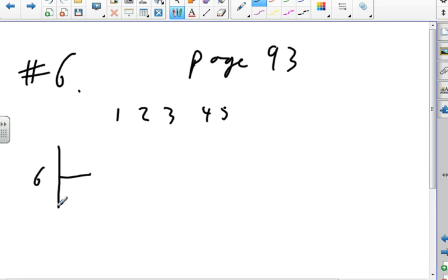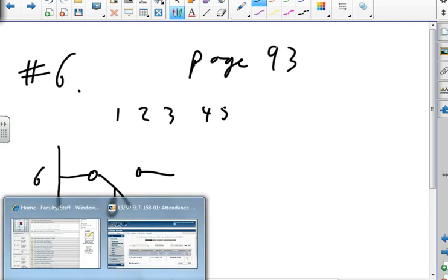Okay, so we're going to have a low level switch. And it's going to close. Alright. It starts 60 seconds after the low level and stops.